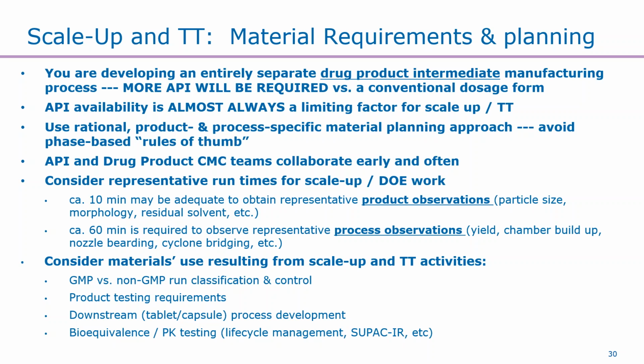And one of the biggest topics that I think you should consider when you're looking at scale up as it relates to material use is representative run times for your scale up and DOE work. So for example, 10 minutes may be adequate to obtain representative product observations, things like particle size, morphology, and residual solvent. But you need at least an hour of runtime to get a representative observation of the process. So things like yield, chamber buildup, nozzle bearding and clogging, and cyclone bridging. So make sure that you understand what your objectives are for the specific experiments and that you have adequate material to